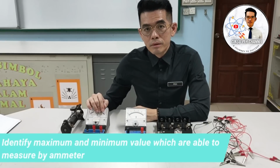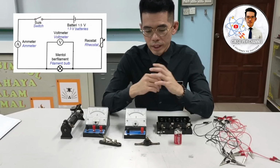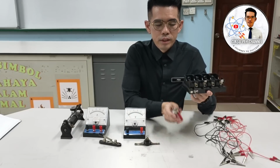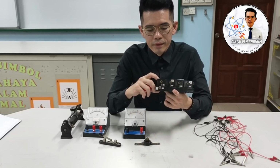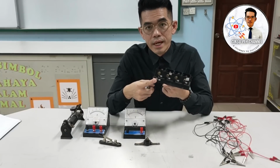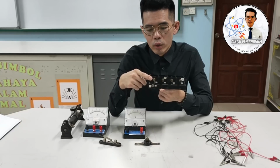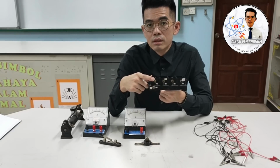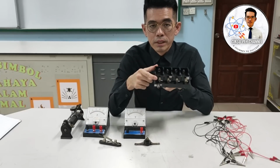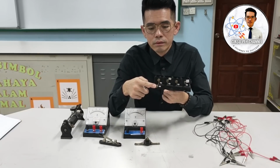To identify the maximum and minimum reading of the ammeter, firstly you need to arrange the apparatus according to the diagram. So firstly, insert your battery or dry cell into the dry cell holder. Here you can see the dry cell holder. There is only one button at the dry cell holder, which represents the negative terminal. And there are 4 buttons on the top of the dry cell holder representing the positive terminal. So insert your battery to the first phase, which is together with the negative terminal button here.